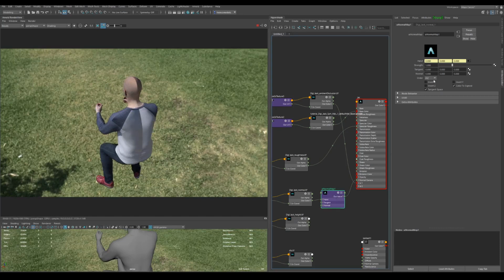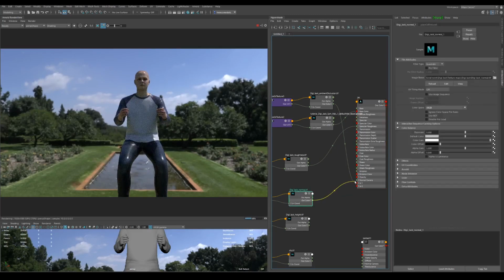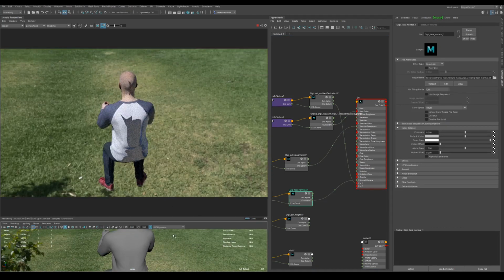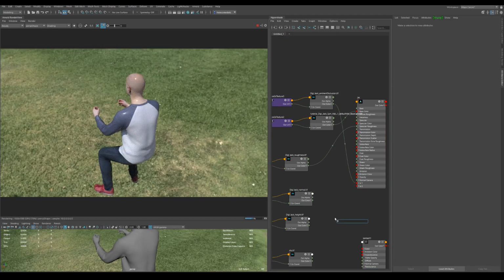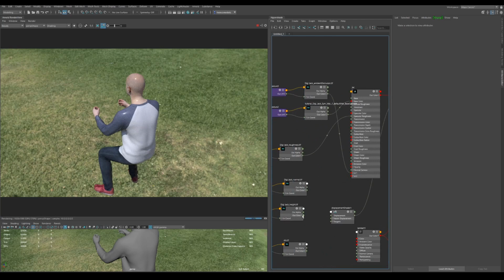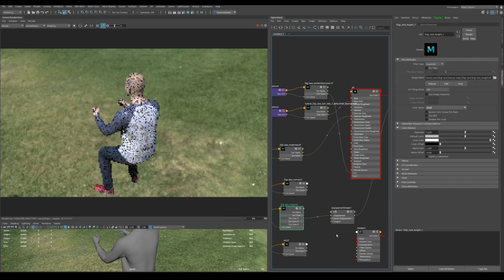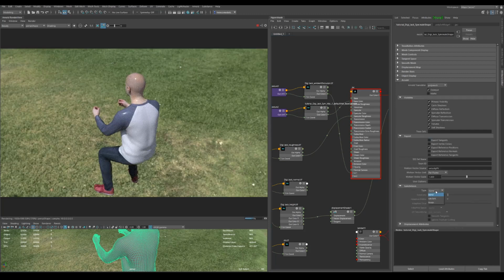However, let's look at the settings in the normal. So let's try using the normal map in the normal camera. Now it's still creating lots of these issues here, which I think might be something to do with lighting because it keeps changing. So instead of that, let's use a displacement shader and plug that into here. So we can use the height, and this is the one that Alchemist created for us. So let's see what result that gives us. First of all, let's change the subdivisions to Catmull-Clark and give it 3 subdivisions.